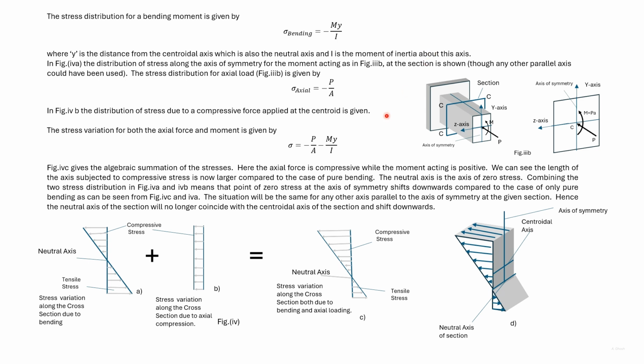So the algebraic sum of stresses on the axis of symmetry on the section CC is given by this expression.